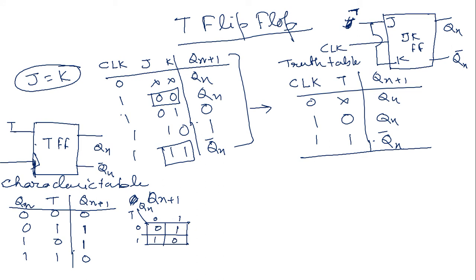So Qn plus 1 equals T Qn complement plus T complement Qn. That is the characteristic equation of this T flip-flop.